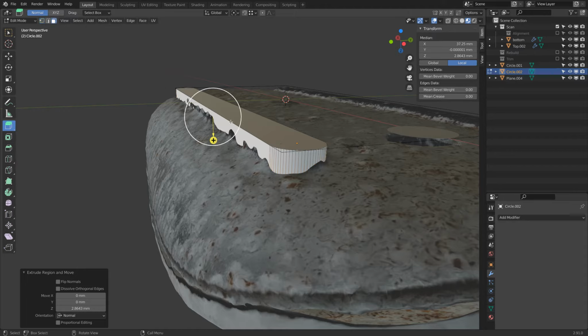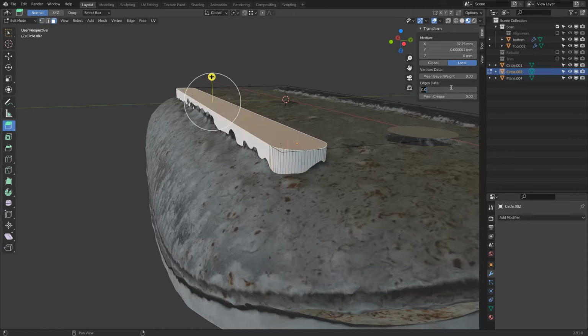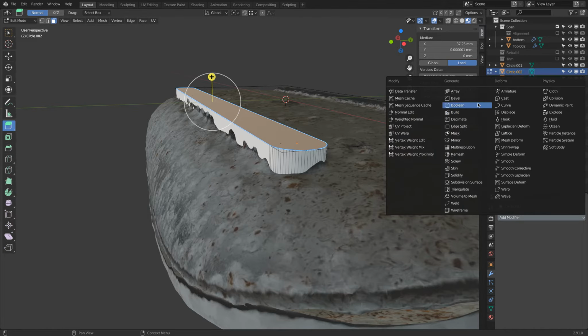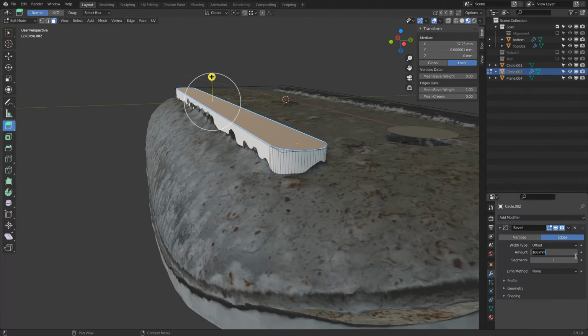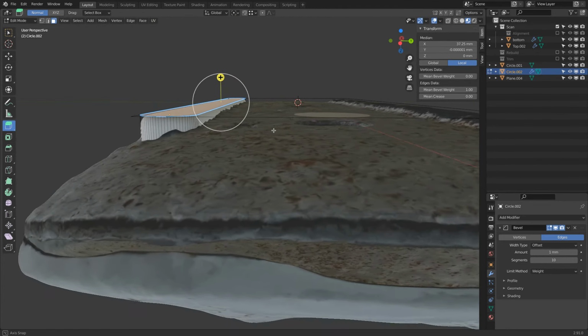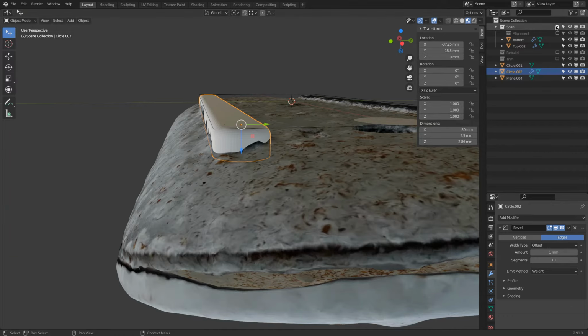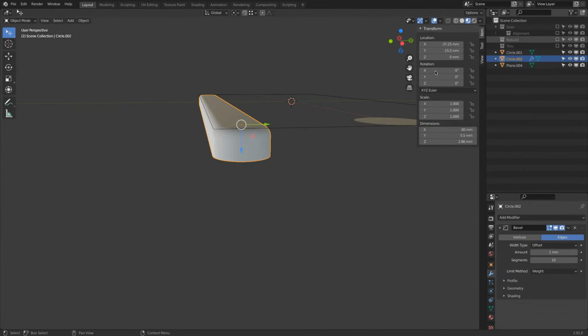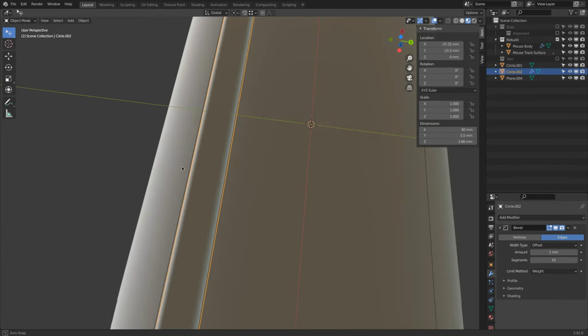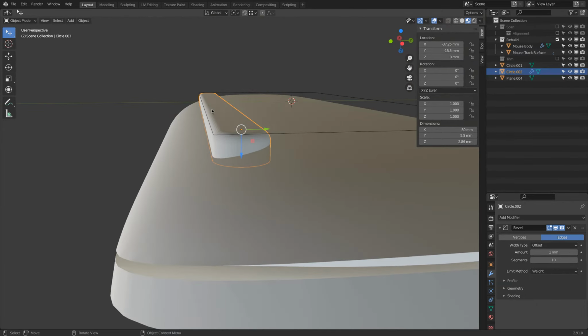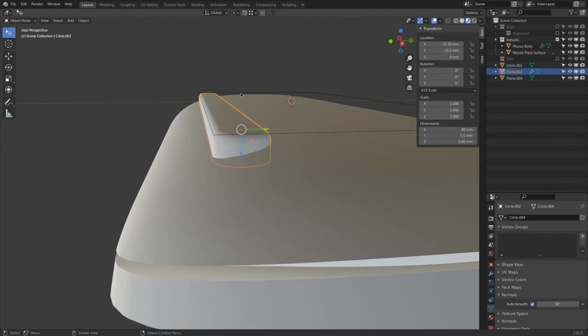So I will go face select this face, say mean bevel 1, add a bevel modifier 1 millimeters, only along weighted edges, 10. Yeah, 1 millimeter might be a little bit much, maybe. Let's see. Oh, we can keep it, it's good. In object mode, right click to shade smooth, and there.